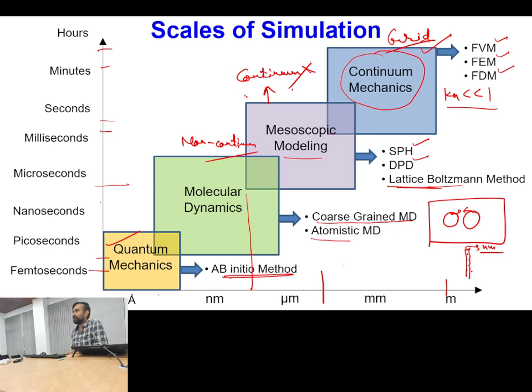So that's why, whenever we solve multi-phase flow problems, most of the time when we are looking at gross parameters, we need not look into such microscopic details. But when we look from the microscopic perspective, say two bubbles are coming toward each other, joining and forming a big bubble, there will be some fraction of a time scale in which the distance between the two bubbles may be of the order of nanometers. During that time interval, some molecular effects can be important. So that's why when we deal with the interface, things become a bit more challenging.